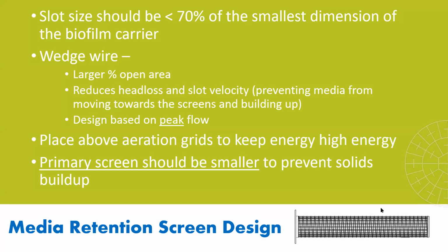One other thing I want to mention is that slot size should not be more than 70% of the smallest dimension of the biofilm carrier. If you have a biofilm carrier that's 12 millimeters wide and you have a slot size that's 11 millimeters wide, yes, the biofilm carrier is not going to move through there, but it can still get lodged into that opening. So we use 70% there.